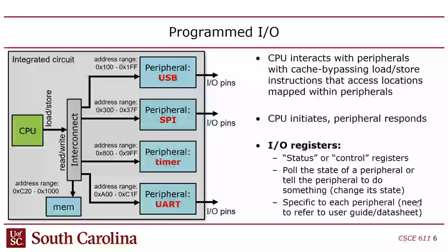They're short-circuited, and instead of going to memory, they go to peripherals, and they allow you to access control and status registers. Now, a control and status register is just a little area inside of a peripheral that you can write to or read from with a load or store instruction to either read the status register or to control the peripheral.